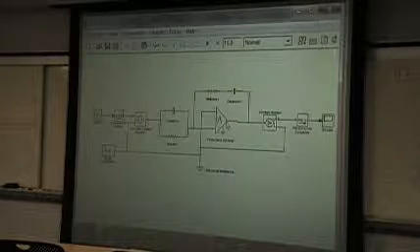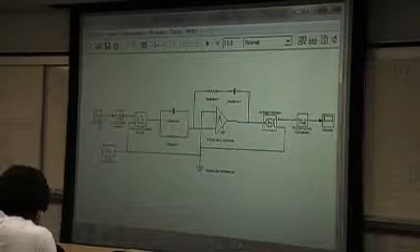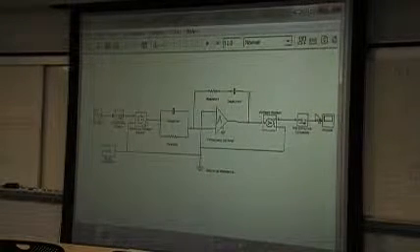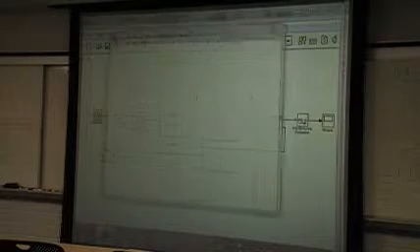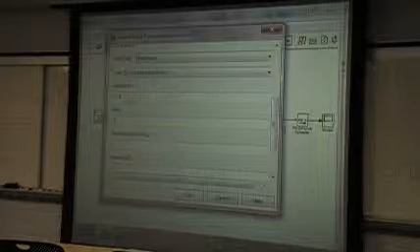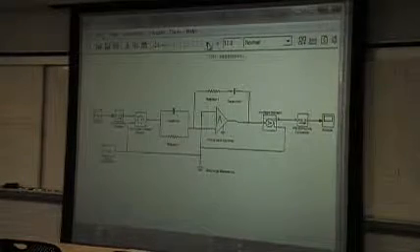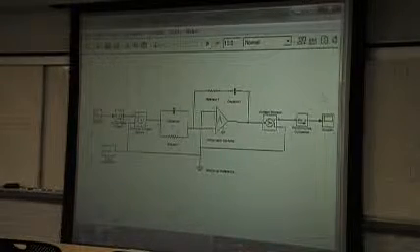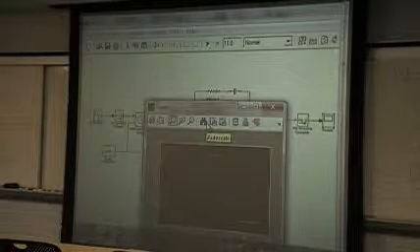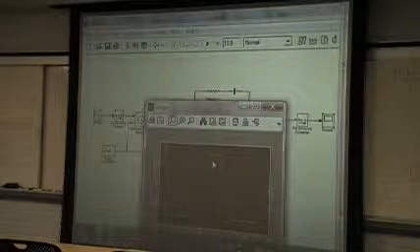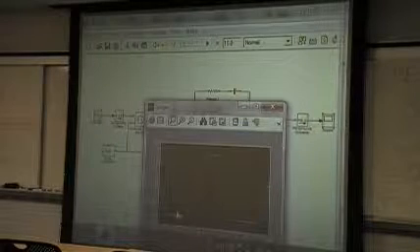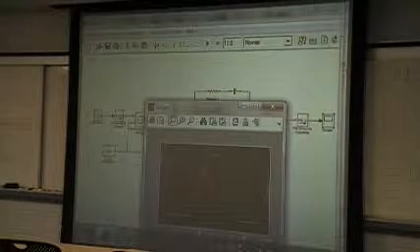And remember that there is an operational amplifier. We have a sine input here, and we are expecting a sine as the output signal. And you can see that the amplitude of the input signal is quite small, 0.3. So what will be the output of the system? If you check it, it should be something like this. Since this is an amplifier, it has a truncation here, or saturation, at plus or minus 15 volts. It is no longer linear.